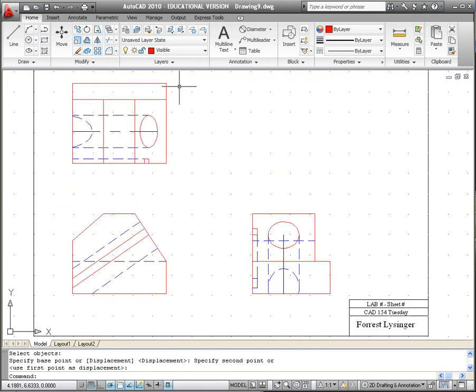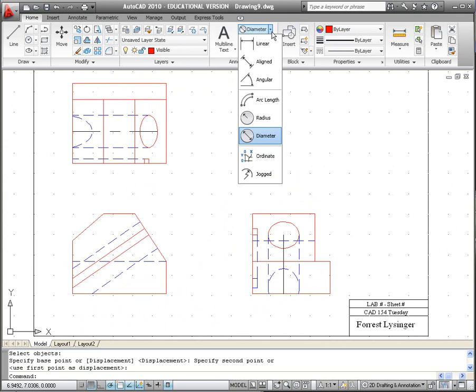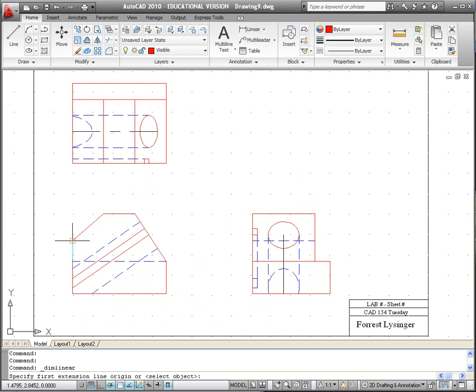So now when you place dimensions on this part, if I go up here and select a linear dimension, I have the corrected English dimensions for the features. So of course, select your layers then, but go and redimension this part in English and see if you can find the setting where you would do a dual dimension for that. That's it.